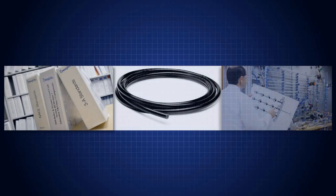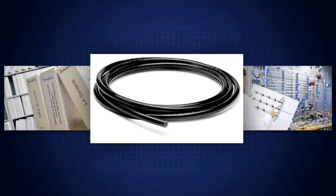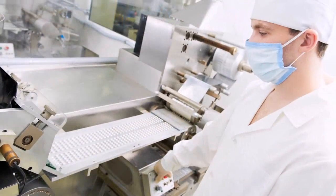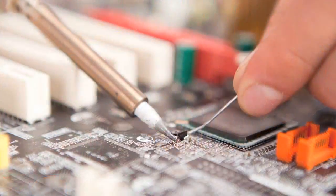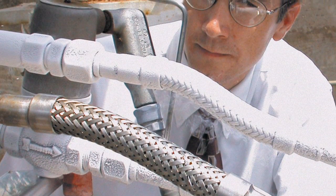There are 3 items to consider when selecting the end connection for your hose: industry standards, hose type, and system specifications. First, let's take a look at some of the industries that make use of hose assemblies. General industrial, typically determined by pressure rating; pharmaceutical, typically determined by the need for a sterile design; and semiconductor, typically determined by surface finish.